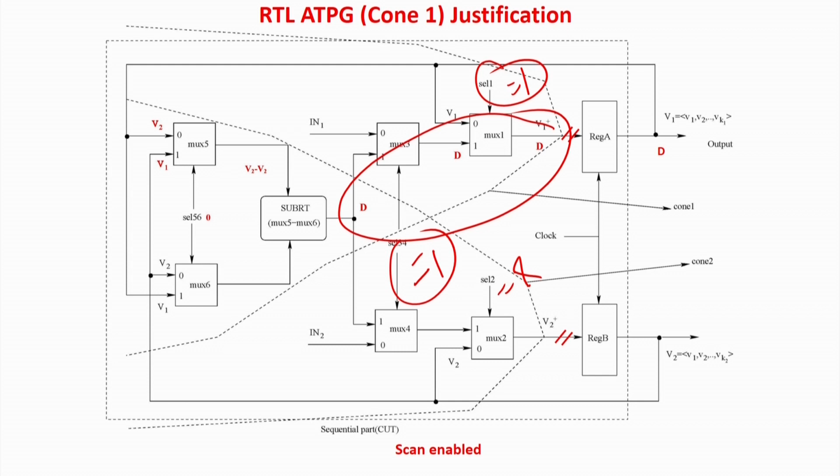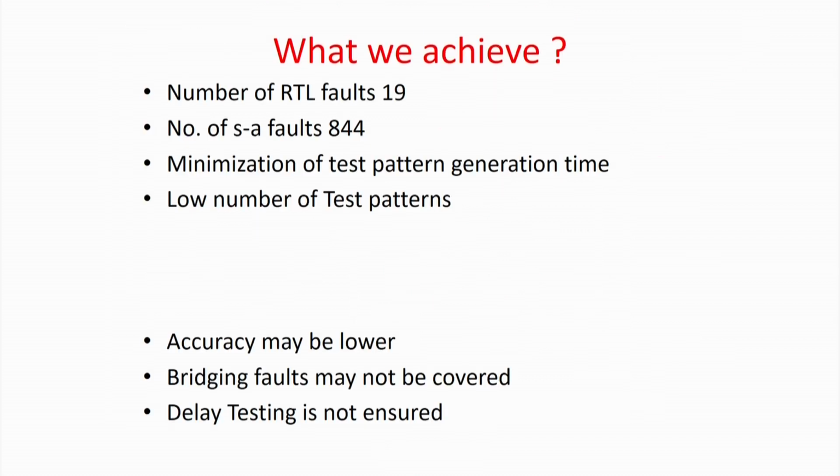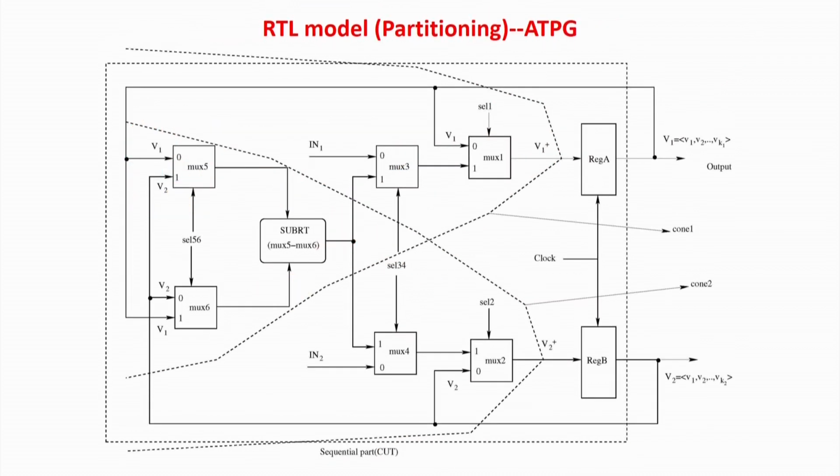So what you do to this latched value, now you will be using a scan. Again you enable the scan and put the value at the output and just check whether it is a non-zero number or zero number. If zero number, this mask has the problem of fault type, else reverse, it is a normal circuit. So the concept is extremely similar, but instead of considering all these numbers as higher bit width numbers, we are considering a single block, single line.